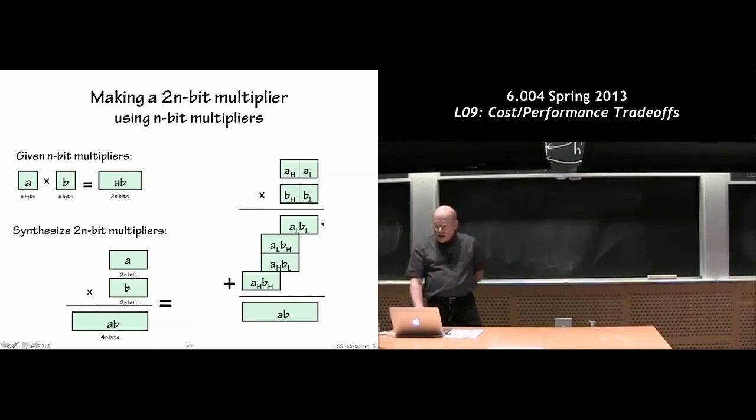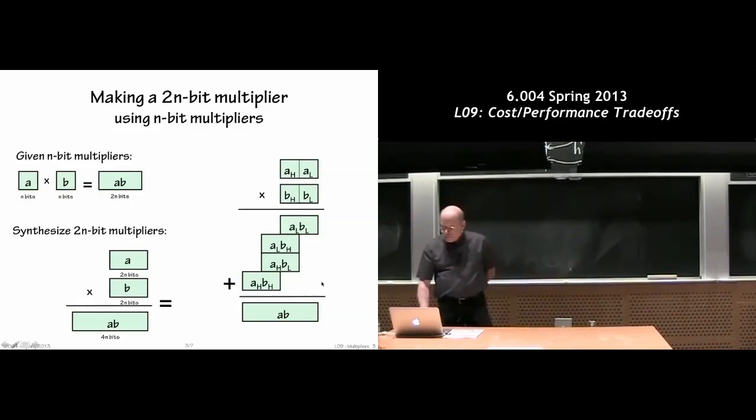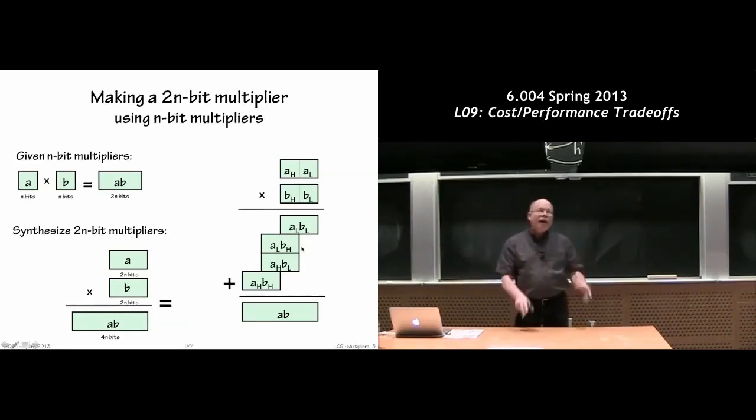You can see we can parlay that skill of being able to do an n by n multiply by basically breaking this big problem down into 4 subproblems, which will create these 4 partial products. One way to think about this is I can use 4 copies of this building block to deal with the A low and B low and A high and B high operands as n-bit operands. Then I'd simply have to worry a little bit about the appropriate scaling, moving things over. So think of this partial product as shifted over by n bits. It's like multiplying it by 2 to the n.